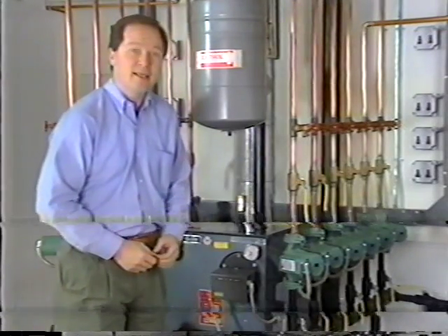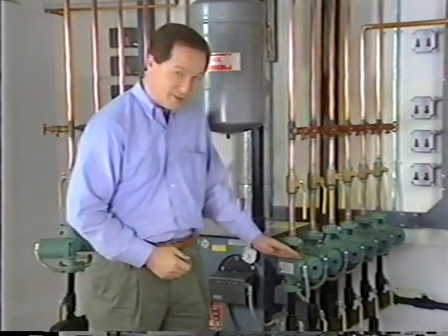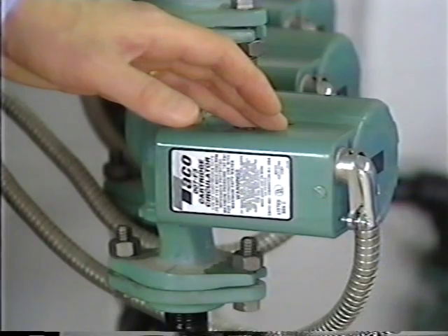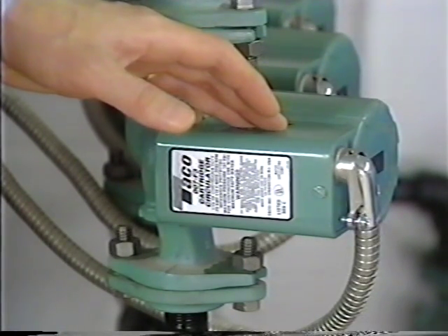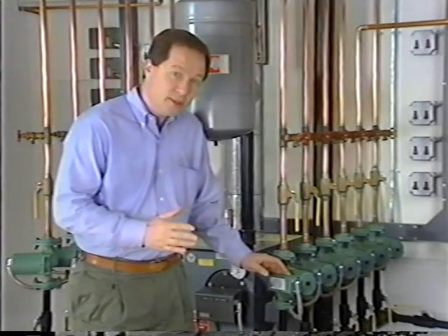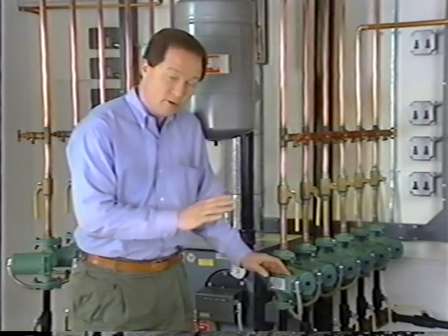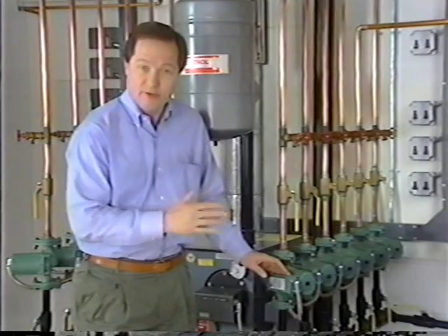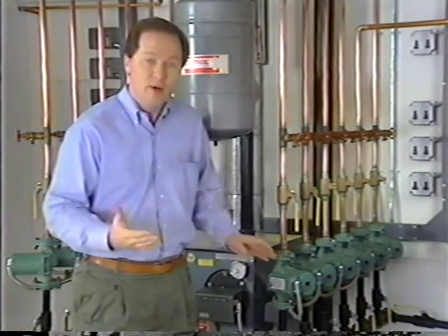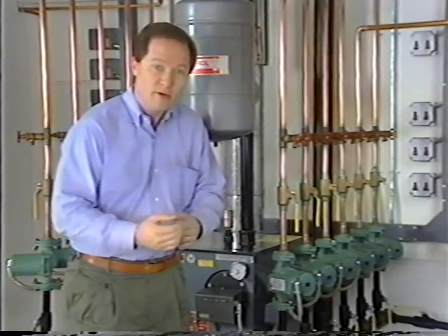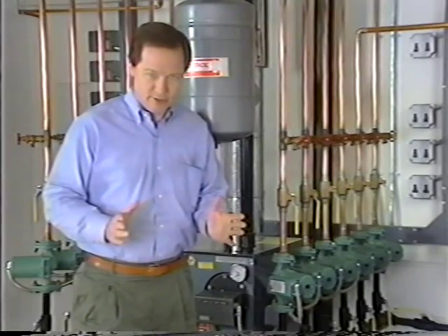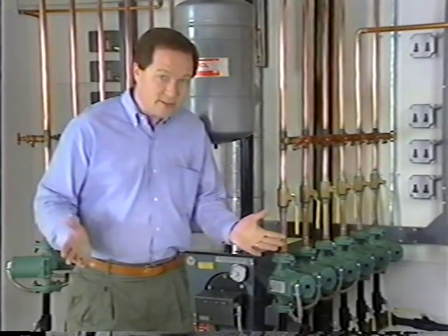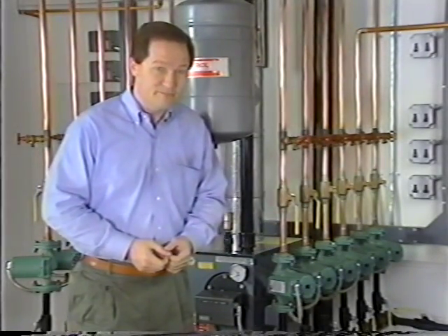Another common hydronic heating component is the circulator. The most common circulators found on residential boilers are single-stage centrifugal pumps. The circulator's job is to force water throughout the hot water system. The circulator contains an impeller with a number of vanes which rotate at a high speed to move water through the system. There are a couple of ways to isolate a circulator so that if replacement is necessary, you don't have to drain the system.